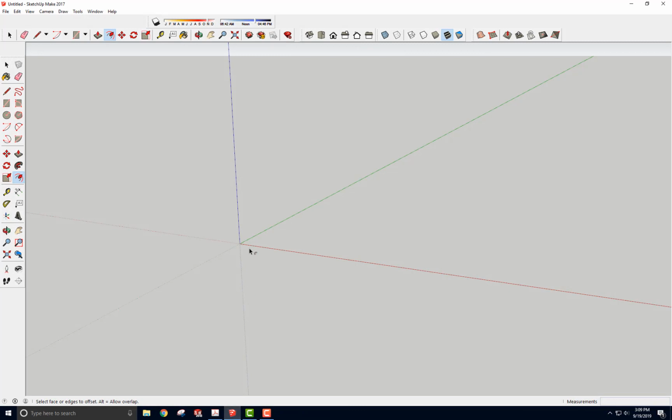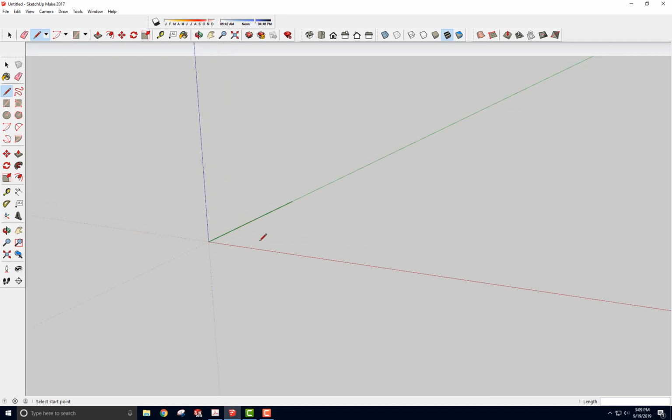So going back to SketchUp, I'm going to start with just a reference to the origin. I'm going to come back with a line that's going to be 4 inches to here, and here it's zoomed out. So here's our line. I'm going to create a surface for the back part, which is going to be 6,1 inches, and there it is. And I'll raise that up 6 inches.